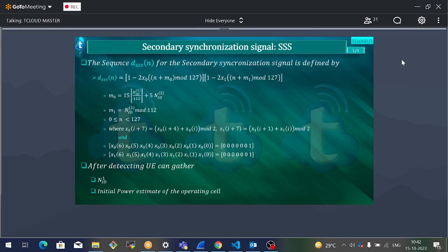Why is it finding out this power value first of all? You remember, I told you that if the mobile equipment found multiple cells, then for every cell the mobile needs to detect the SSB. The mobile might have detected multiple SSBs belonging to multiple cells. Now, out of all these cells, the mobile needs to select in which cell it is going to operate. For that cell selection, the power values that the mobile estimated on these SSS symbols would be useful. Of course, if the mobile equipment is near a cell, the signal strength would be a little better. Otherwise, it is a little low.